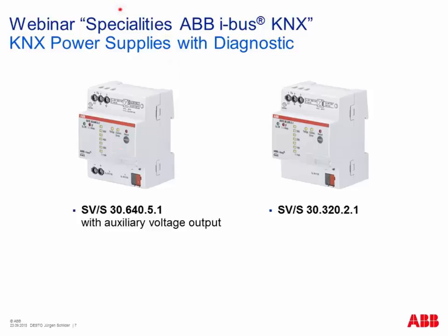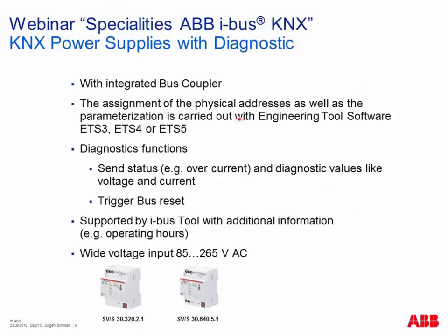But furthermore, it's a KNX device, meaning not only a simple power supply, but one with an integrated bus coupler, which allows you to program such a component with physical address, but also with parameters and group addresses, with an application which allows you to read out the status information of the component directly via the bus. For example, overcurrent, and the actual values for voltage and current, everything can be transmitted via KNX, for example to any visualization, to check whether everything is correct with this power supply and the line behind. So this gives you an additional feature, let me say safety, for a KNX power supply.